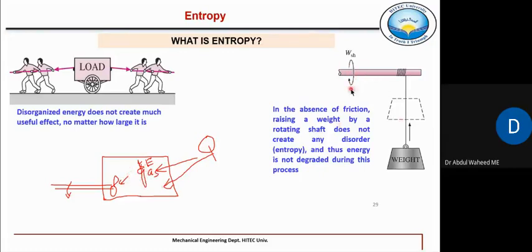When this shaft moves, all the molecules are actually moving in one particular direction. So here we have a more ordered form of energy, or this work. And that energy which is transferred is known as work. So it means work is free from disorder or randomness, right? Or in other words, it is free from entropy. Okay. So no entropy is transferred during this transfer of work.